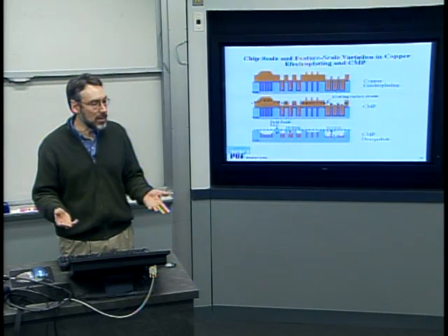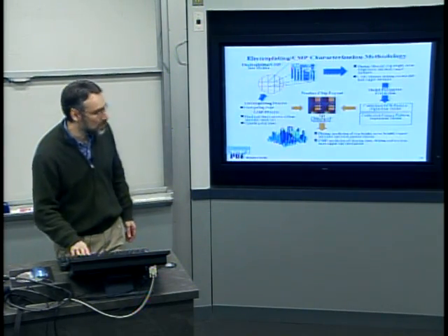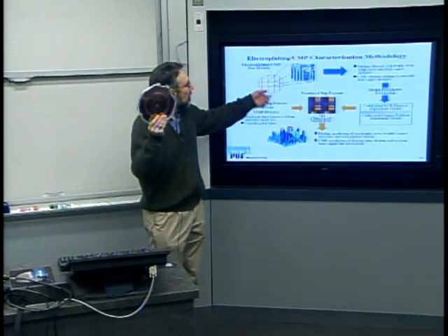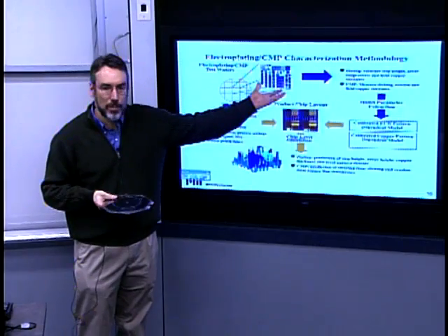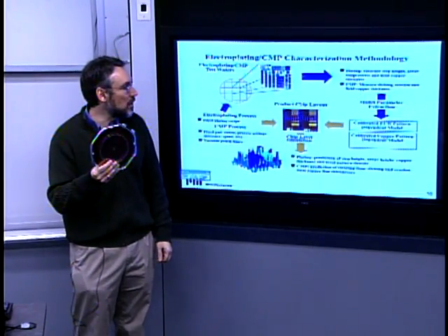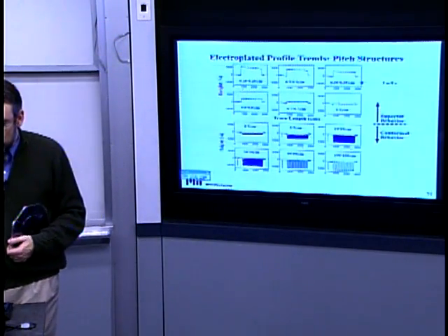They are manufacturing limitations, and one would like to model and characterize those. And in fact, that's what this wafer was for. What we came up with was a test structure methodology where you would put lots of features of different sizes on a wafer, run it through the process, measure the results.